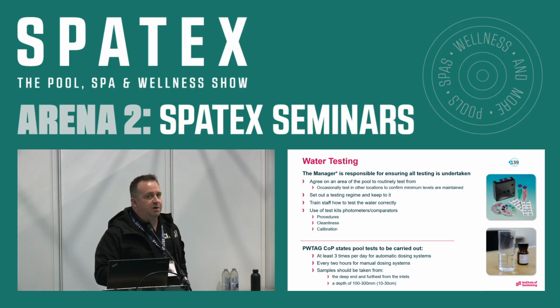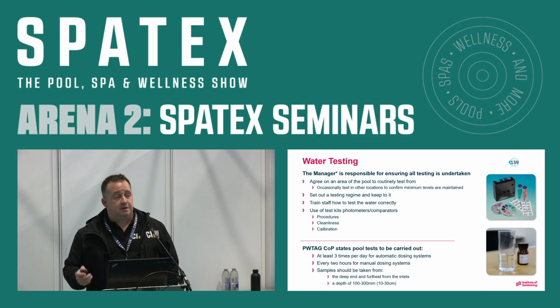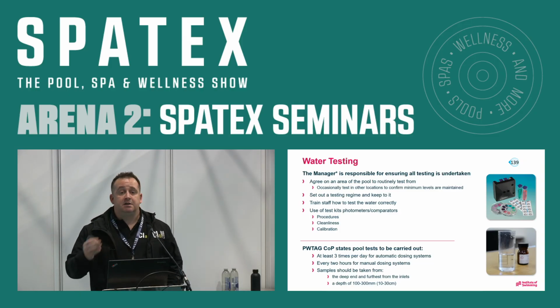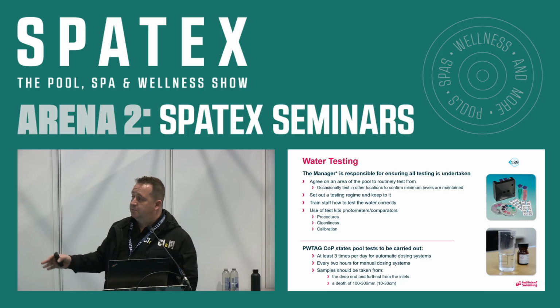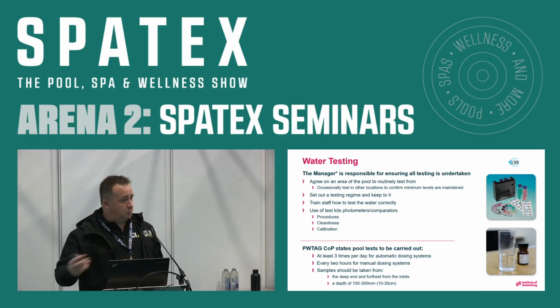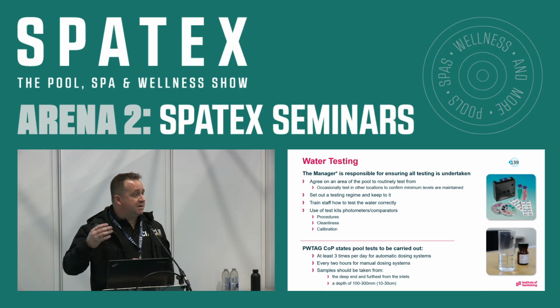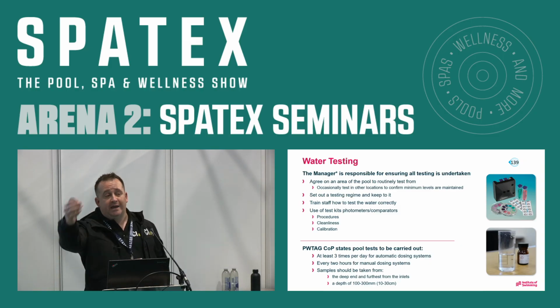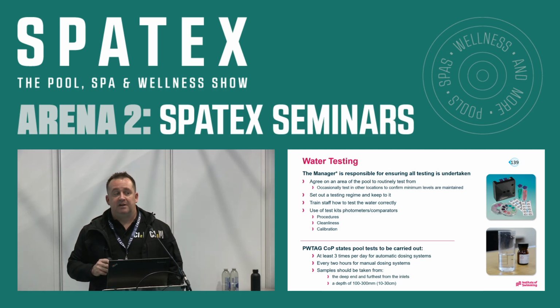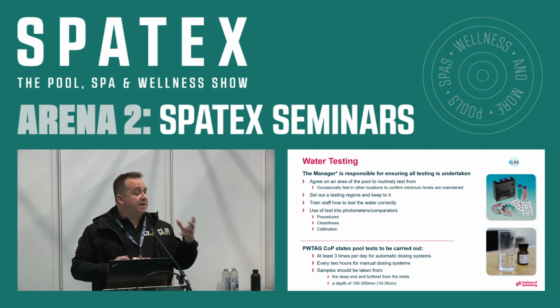Samples should be taken from the pool, always from the swimming pool. Engineers will quite often take one from the sample tap from the control unit if they want to calibrate the control system. But we need to take our samples from the pool itself and look at your swimming pool. Look where the water comes in, look where the water comes out. Okay, you only take the water sample from the furthest point away from the inlets, so the worst possible part of the pool. If you can keep that golden, okay, then you're good to go.